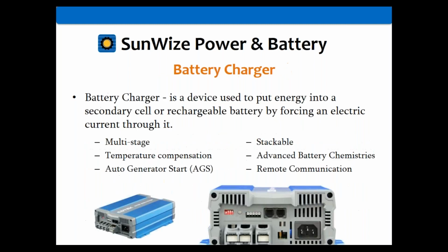Now, the nice thing about a battery is that it kind of acts as a filter, to be honest. It's got a giant capacitor in there with the plates. So sometimes the battery can actually help to filter that out, which is why a battery charger is what you should use for charging batteries. Now, there are some caveats. Sometimes you can get away with using a power supply to charge a battery if it's done a certain way. And obviously, sometimes with the battery there, you can use your battery charger to support your load, making certain you have things that are working correctly together.